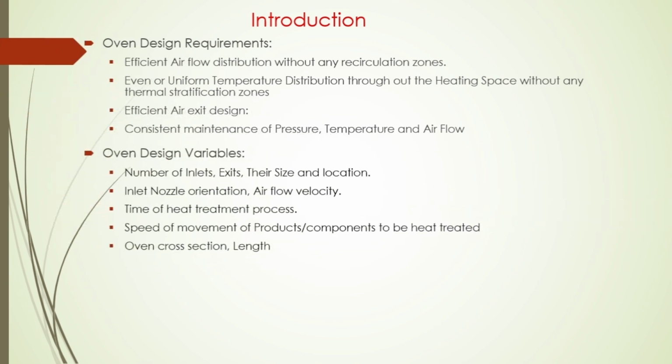The design variables which influence the above criteria are the number of inlets, number of exits, their size and location, inlet nozzle orientation and the airflow velocity, time of heat treatment process, speed of movement of products or components to be heat treated, oven cross section and length.